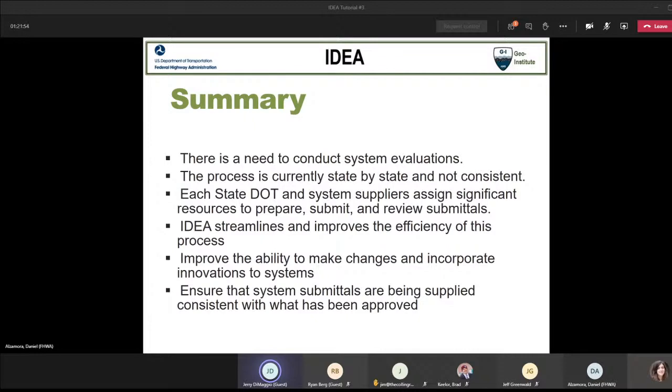At one time, there was no such thing as understanding what design life protocol meant. And that applies to both geosynthetic as well as metallic reinforcement. The concrete strengths on facing panels were significantly less than what the standard of care is today. The joint material was very different, not only the material type but also the engineering characteristics.